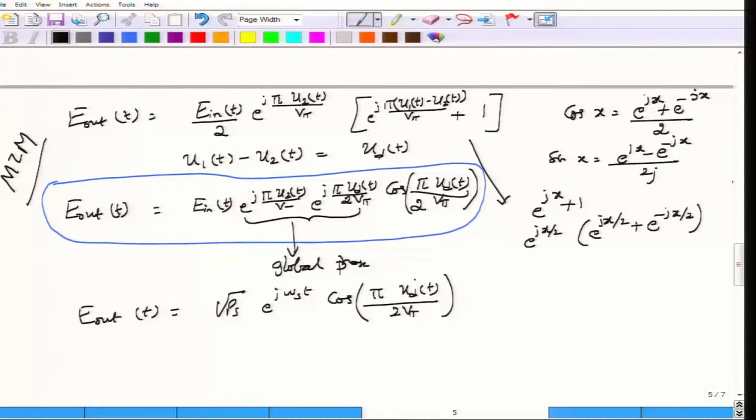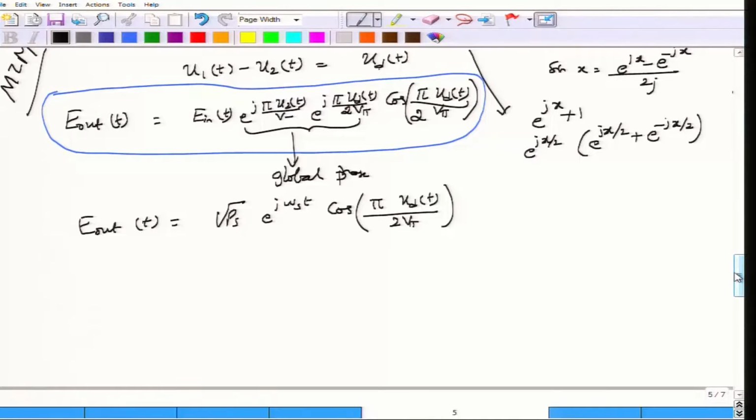Have we obtained amplitude modulation? Well, not quite yet, because in an amplitude modulation, as we normally understand, the signal s of t after modulation would be written something like A_C cos(omega_s t), which would be the electrical carrier signal, multiplied by u of t, where u of t is the message signal. This is what is called a double side band suppressed carrier, if you remember. So, I have not yet quite obtained that. Just to make it consistent, let me write this as u_d(t) being the message signal, the equivalent of the message signal.